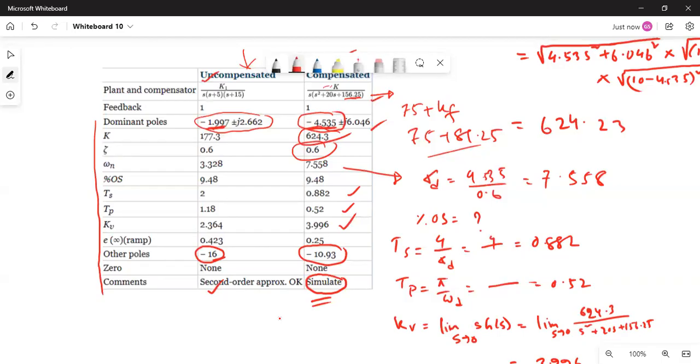So this is your second approach of designing the feedback. The first approach was similar to the cascade, and this approach is based on 2 separate root locus designs. We haven't introduced any pole and zero. We've just changed the location of the poles of the minor loop. Then based on the gain of the minor loop, whatever poles we have obtained, based on that we have designed the major loop. So 2 separate gain adjustments we have done.